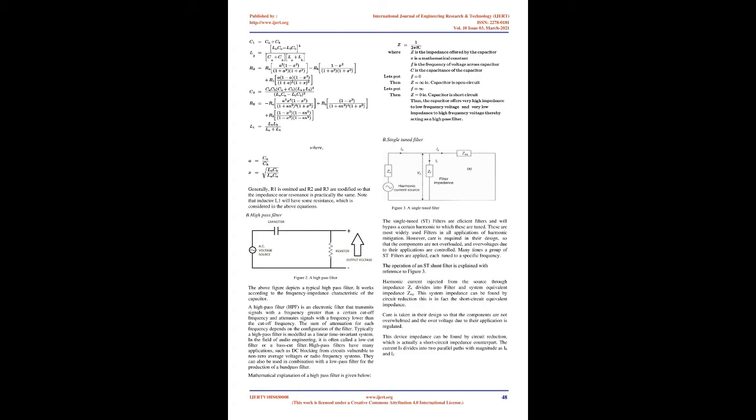Double-tuned filter. A double-tuned filter is derived from 2 single-tuned filters and is shown in Fig 1. The advantage with respect to 2 single-tuned filters is that the power loss at fundamental frequency is less and 1 inductor instead of 2 is subjected to full impulse voltage. This is an advantage in HV applications.